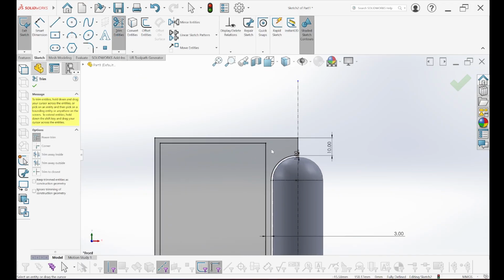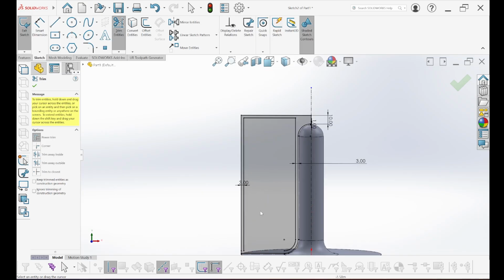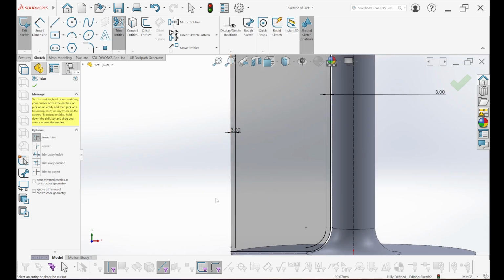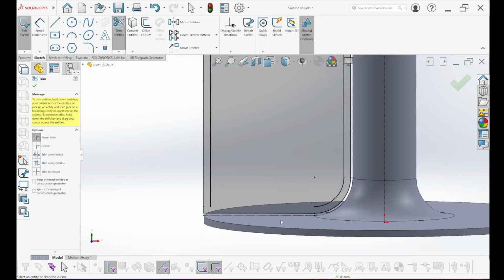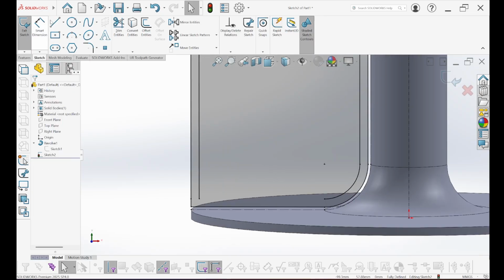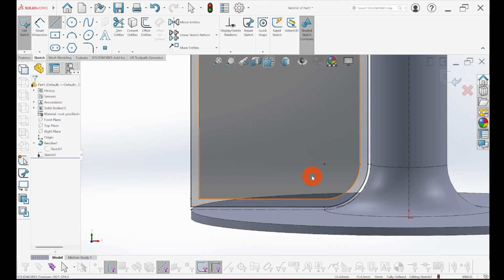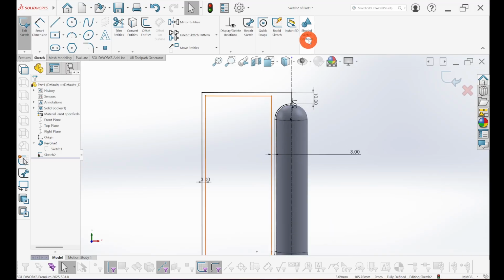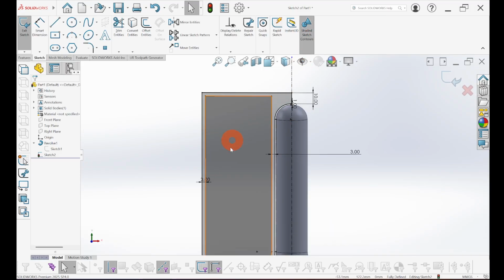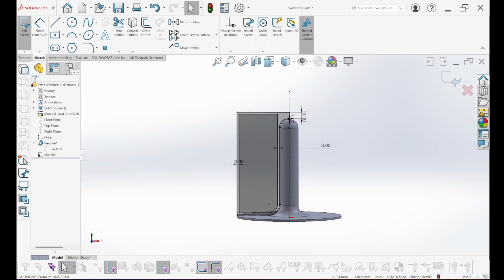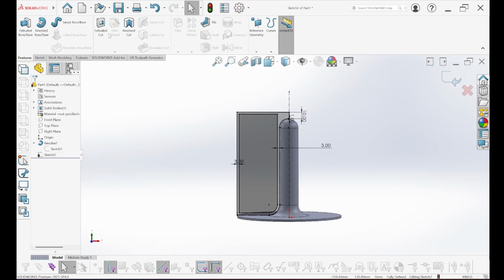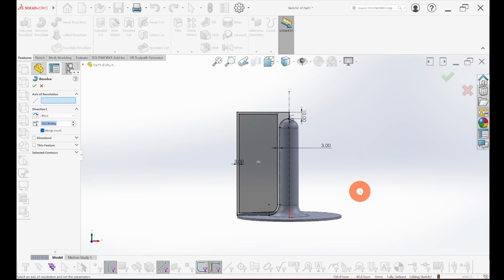So this way I'm gonna have a strong top, hollow interior. And here we're gonna add the pins to carry the bobbins. And here we need to complete that line that I deleted by mistake before. So I'm just sketching it again, and that's it. We can see that with the shaded sketch contour, we have the two areas inside each other. Features, revolve. It's asking me where is the axis.